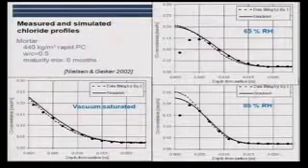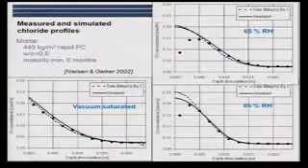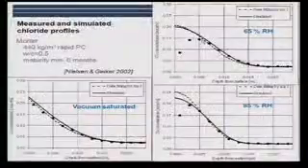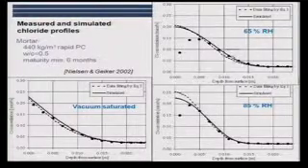And then we predicted the diffusion coefficient based on these volume considerations. How much capillary porosity would we have after 6 months in this mix? How much of the capillary porosity is saturated at the condition we are looking at? And these are the simulated values, and then we measured the chloride ingress.